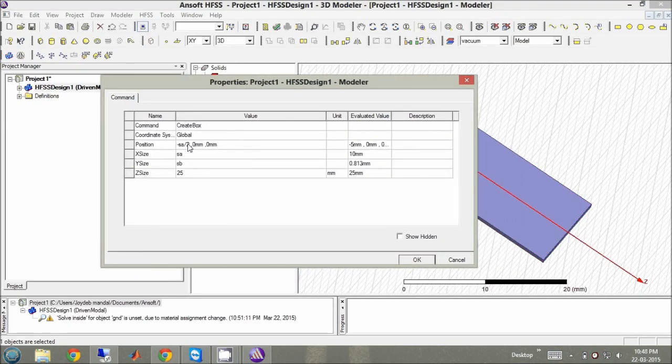By the substrate dimension, so you have to redesign it. Same. Y size will be minus of TH. Means earlier the substrate started from 0 and here it is now minus TH, means 0 to minus TH. This TH means ground plane thickness, very thin copper.